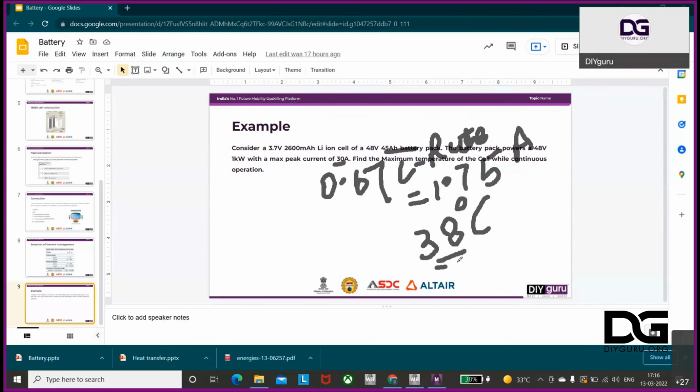So for the whole question, I got my answer through analysis, which was very practical based. So I can assume that my battery pack is not going above 50 degrees Celsius, so that is safe. Now if I take this for an individual cell, not considering the battery pack, at one C rating of this cell, if I calculate Q, going beyond the question for demonstration purposes, I'll take 2.6 squared into the entire resistance.